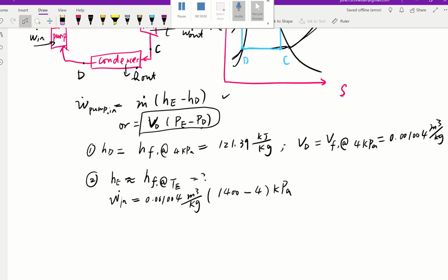All right, now before we put things into calculators, think about the unit. Kilopascal times meter cubed: kilopascal times meter squared, that's pressure times area, which gives us force, and then force times meter is distance, so that's energy, kilojoule. So the whole thing is going to give us a unit of kilojoule per kilogram.